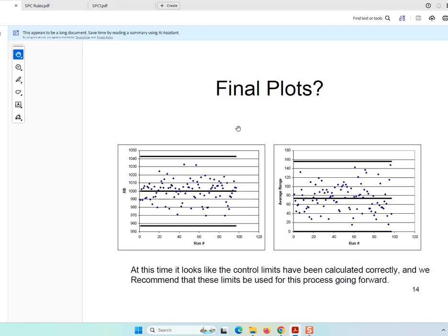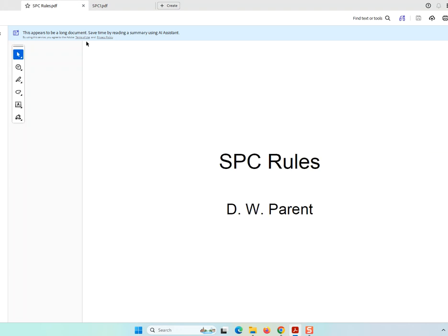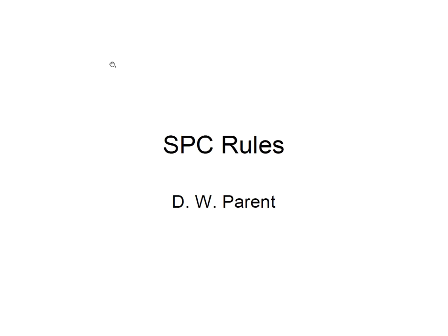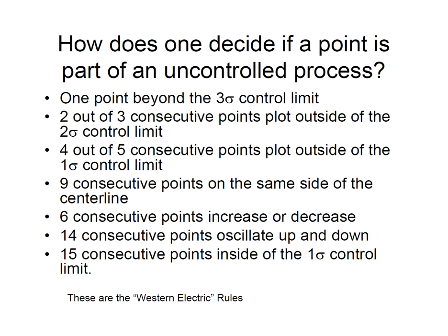And again, we're still trying to be somewhat intuitive with this. I can understand that this is not easy. So now we talk about, is it in control? Is it out of control? Is it random? And then we have statistical process rules, and these come from Western Electric.